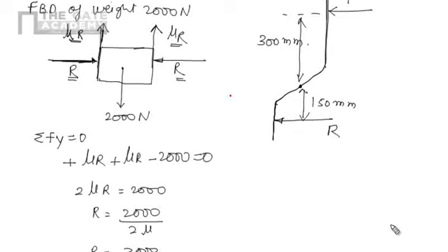Now if we consider the frictional force here, the direction of this frictional force will be in that direction, that will be mu R. And the distance between the hinge and this is very negligible, so the moment caused by this will be negligible. Now we can directly apply condition number 3, that is the algebraic summation of moments of all the forces about O should be 0.